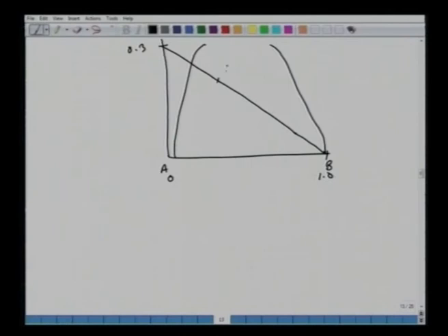Or mathematically you can solve. You know this amount of R1. You know this B. You know the compositions here. Find the new M2 and find the new tie line which passes through this M2 here. In this case, we can show that your xM2 will be equal to 0.18, and the amount of raffinate will be 90.1. Extract E2 will be 46.3. If you add these two, this should be 136.4 kg, the amount of raffinate which we started with.